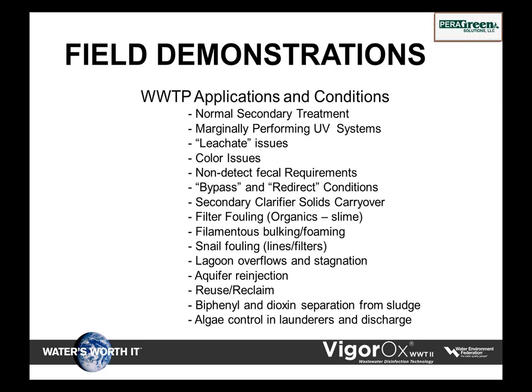Snail fouling. This is something that we found in New Jersey. It'll clean the lines out. It'll clean all the equipment out. Snails do not like PAA, and they're going to find a way to get away from it. You'll see snails climbing the walls to get away from the contact with PAA.